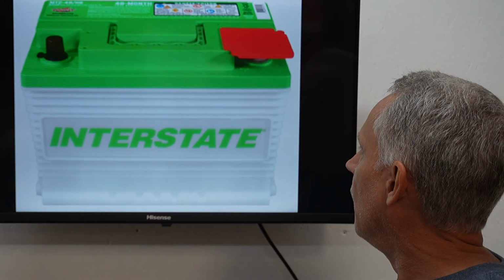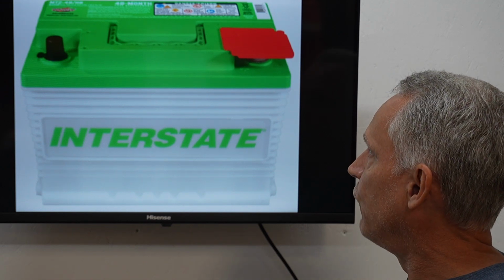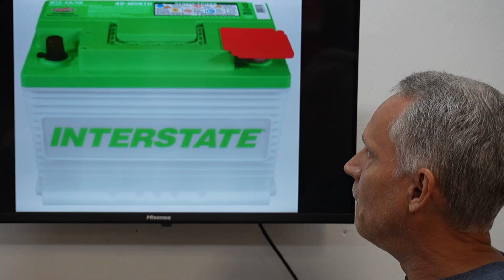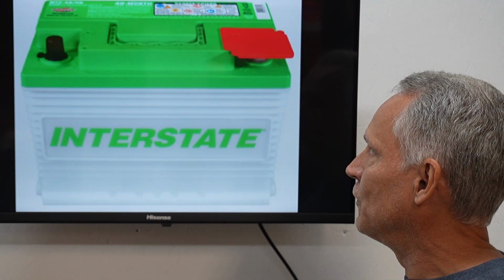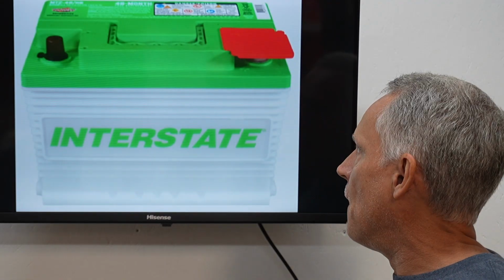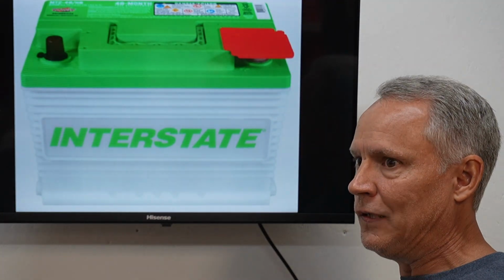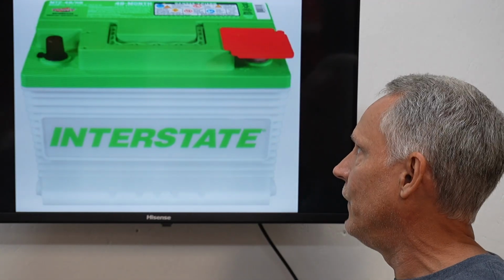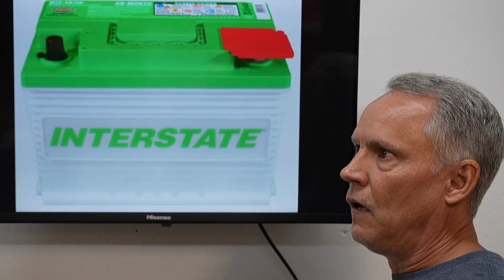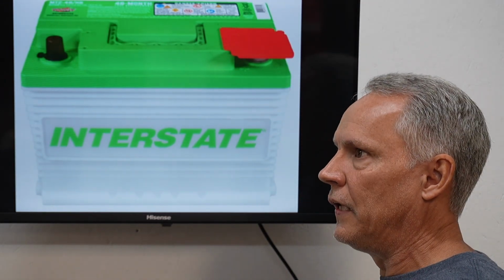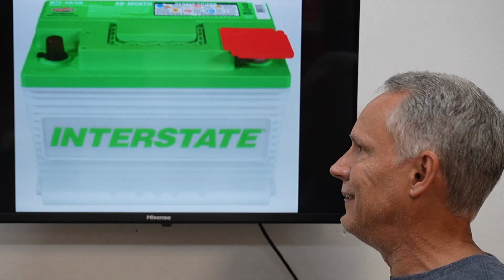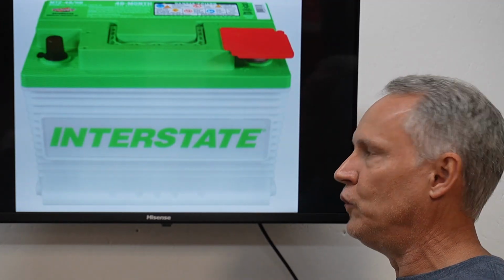Okay, same thing. Lead acid battery, flooded lead acid battery. You really can't service the electrolyte, so it would be considered sealed. But that being said, it's not actually, once again, an SLA sealed lead acid type of battery. That nomenclature, SLA, VRLA, relates to AGM batteries and gel cell batteries.